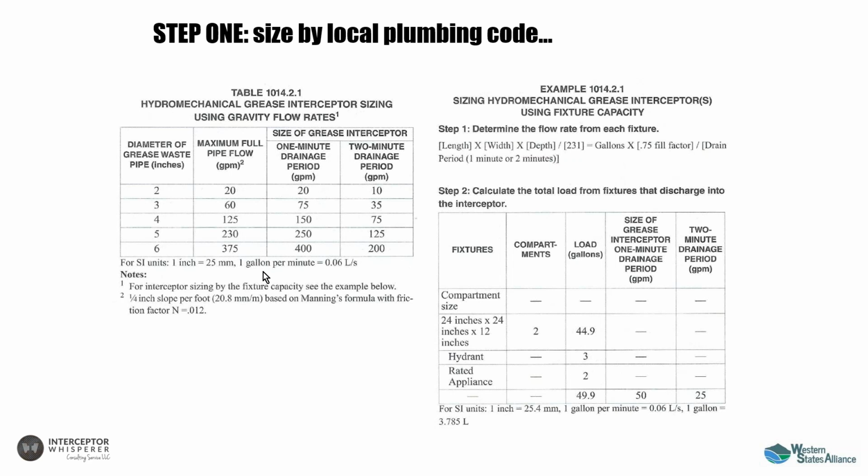The challenge with applying drainage fixture units to a kitchen, though, is you're going to have some sudden massive volumes that can come together at very high rates for very short periods of time. And so you have to make a decision about whether to use a 1 minute or a 2 minute drainage period. A 1 minute, as you now know, would suggest that this pipe is capable of delivering. Once you get outside the building, we're not going to see 1 minute volumes of water. You've got too many feet, what we call developed feet of pipe. There's too much of that, and so you don't see these kinds of flow rates outside the buildings. And if you look at the WERF report, they've analyzed flow rates coming out of buildings, and they never saw anything greater than about 45 gallons a minute.